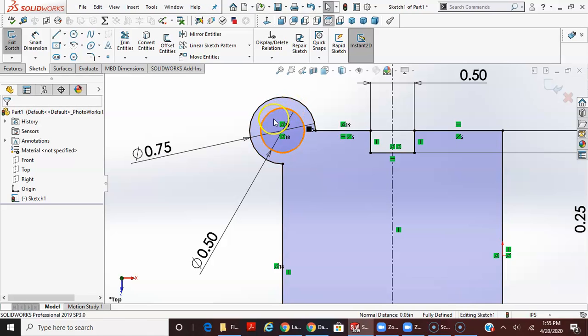They use the term imply, but you can see on the drawing that this center mark does line up with this edge. If you actually take your drawing, you can fold the bottom edge of the drawing perpendicular to the side edges, where these two lines are collinear, and then it will line up with this center mark, both vertically from this edge and then horizontally from this edge.